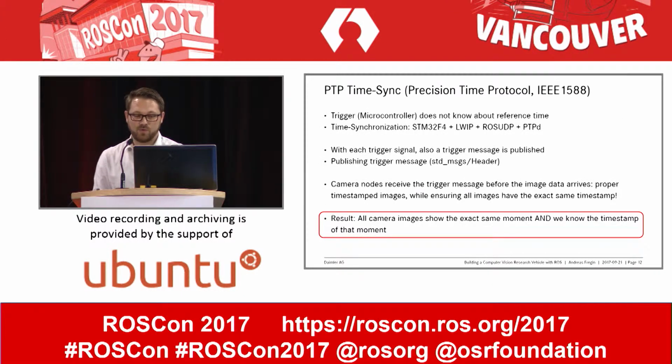In our case, we migrated our Arduino triggering microcontroller to an STM32F4-based microcontroller, and for this kind of microcontroller, Bosch showed on ROSCon 2015 a ROS implementation. This project used the lightweight IP stack (lwIP) in conjunction with a self-written XML-RPC server and a ROS UDP implementation to directly publish and subscribe ROS messages without the need of a host PC. We adapted this solution and added the Precision Time Protocol (PTP) to the project, which enables us to publish stamped trigger messages that use reference time as well.